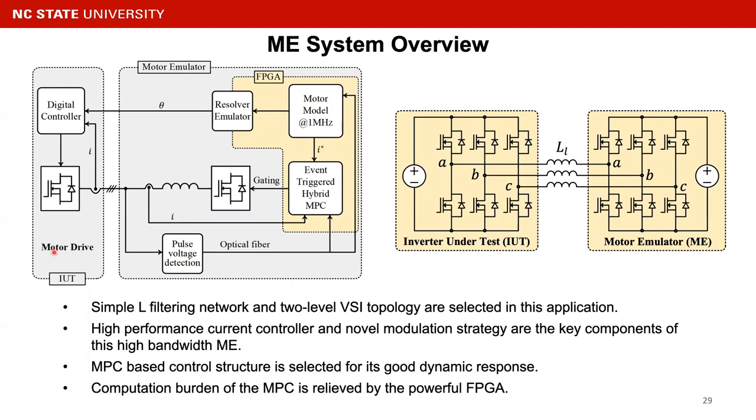First we have the inverter under test, and then the motor emulator would sample the output PWM voltage by the IUT. And then the embedded motor model would calculate the current which should exist in a real motor. And the high performance MPC-based controller would regulate the current through the inductor to follow this current reference.